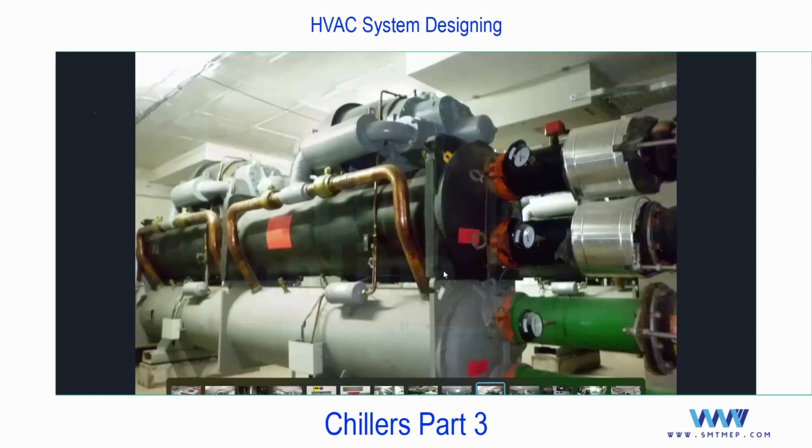You see this, like a complicated machine. Can you identify these 2 different shell and tube heat exchangers? Here, this is 1 shell and tube, and this is one more shell and tube. And you'll find multiple compressors and the expansion. So the same components: compressor, condenser, expansion, and evaporator, but the condenser as well as the evaporator are both of the same shell and tube type. Now, can you identify which is the condenser and which is the evaporator in this image? Any guess? Below one white, it is the condenser, and back.